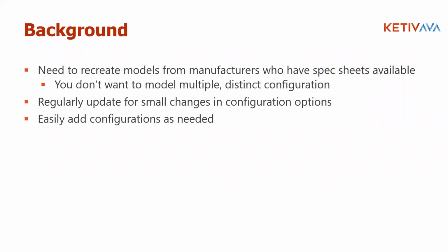So looking at generative design, as you know, you make a configurable model and you have lots of options for it. And some of those options match other options. And this is all done through parameters. So you put together a model that's got parameters, say that maybe have length and width and height, and maybe they have some features that are present or not present. And maybe those features can move around in the assembly or the part based on some of the inputs. Long story short, you're doing something so you don't have to create this model over and over and over again. You can just fiddle with your parameters and get the one you need.